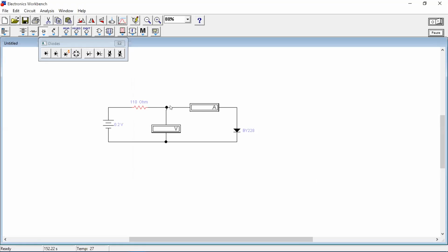Now again you have to follow table 2 and give the inputs and take the voltage value and current value, that means the ammeter value and voltmeter values. After that you have to draw the same graph like the silicon forward characteristic, and I will show it.